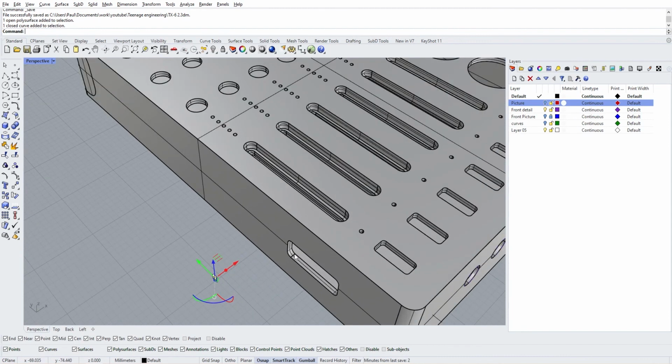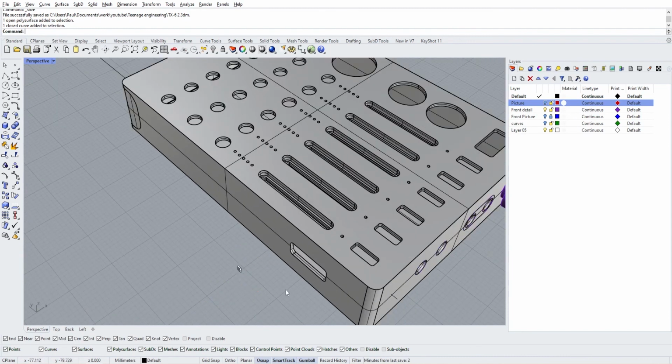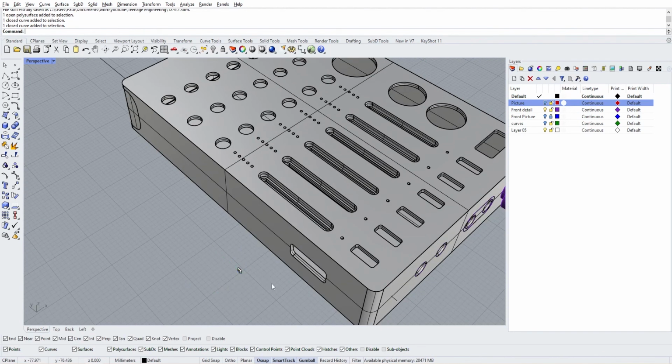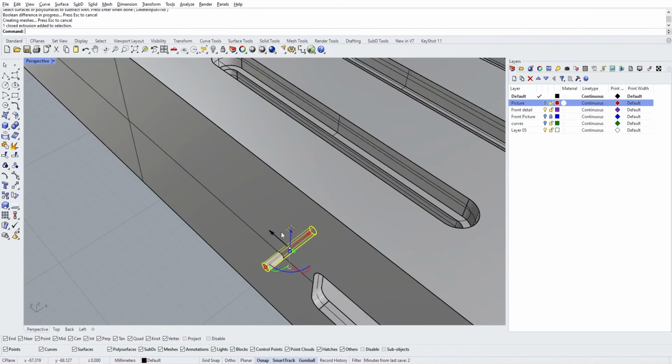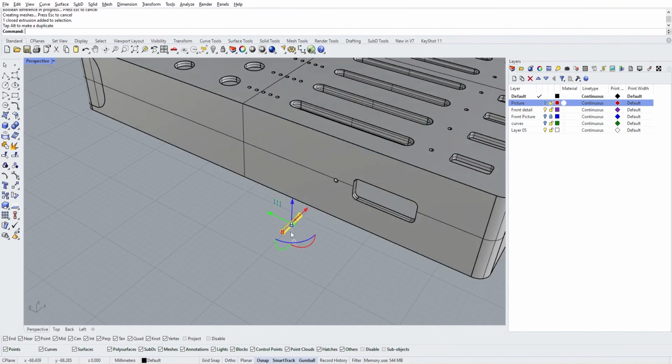So now that we solidified our objects, we're not going to just trim through it. We're going to basically extrude this curve here, and we will use the Boolean tool, so subtraction here, Boolean difference, sorry, in order to cut this with that. So when you select this and you have selected this before, then you can just select the part you want to remove, press enter, and then it will have created this hole inside.